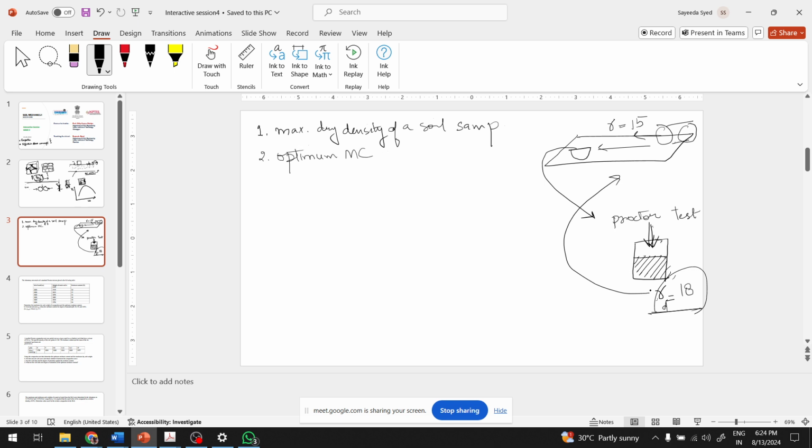Again, from the Proctor test you calculate at what moisture content this soil gets its highest density. So you sprinkle water on the field, you try to get this soil to this optimum moisture content, then you roll for the best results. So this is how you translate what you found in the lab to the field.